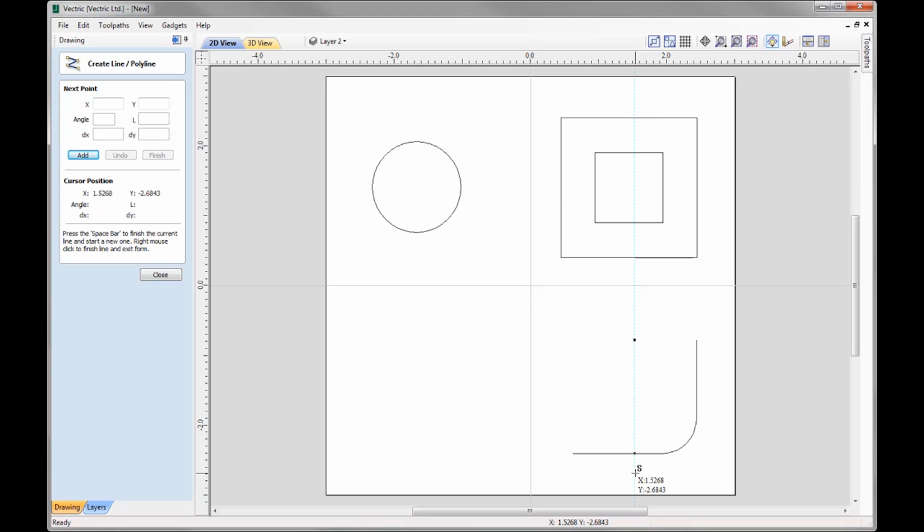So when you see a blue line, that's the software's way of telling you you've found an object bound. In this case, we've found the center vertical line for the object that we've woken up. Again, if I move my cursor, you'll see we've found the right object bound for the object that we've woken up. If I go up, we've found the bottom object bound, the center horizontal line for the object there, and we've found the top of the object, and again we've found the right hand side, the center, and the left hand side. And so having access to all of these lines just makes it easier for me to accurately draw new shapes that are aligned to other objects.